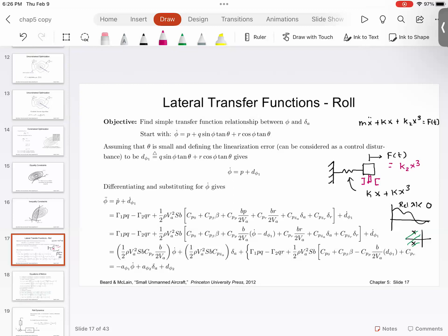So what I would do is measure the displacement of this mass using some type of a pickup, or as a matter of fact, the disturbance in the electromagnet can be used to measure the relative displacement. And then I provide the feedback k2 x cube. As soon as I substitute k2 x cube feedback, my dynamical equation of motion is now converted to mx double dot plus kx is equal to 0.